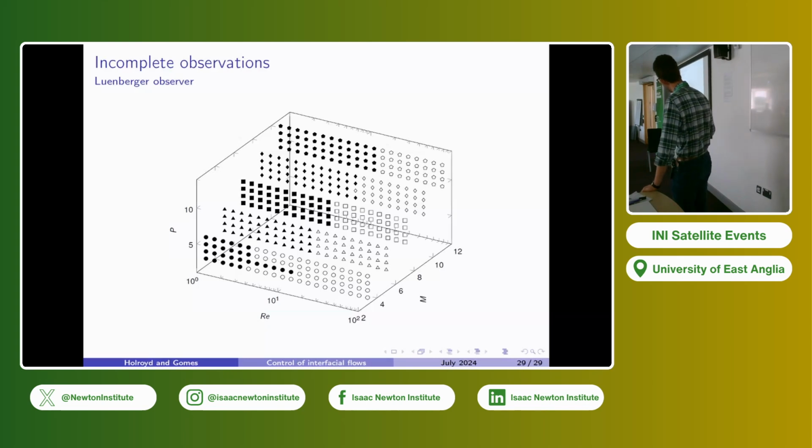But unfortunately, you notice that we no longer have access to these high Reynolds number regimes, well, high for thin films at least. We can't do control here anymore. And that's unfortunate, but this is because we're not only needing the thin films' weighted residuals for the control, but we also need it for the estimator. And so the combination of the two starts to break down if you have thicker films or more viscous films, or whatever. Less viscous. Yeah, less viscous.